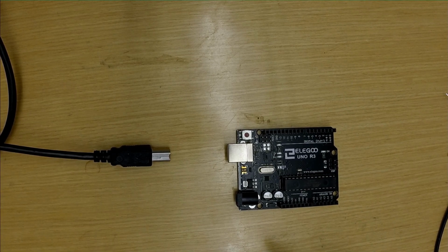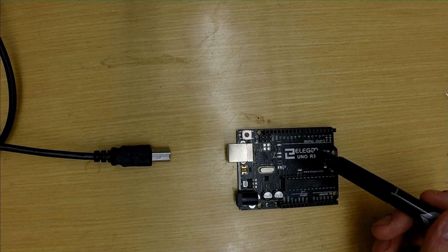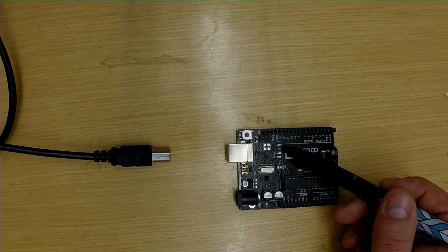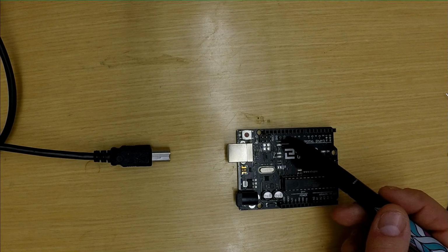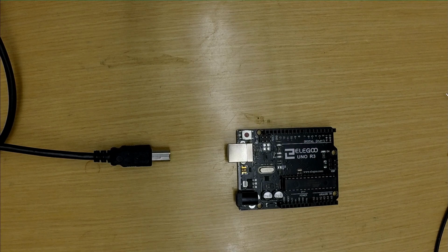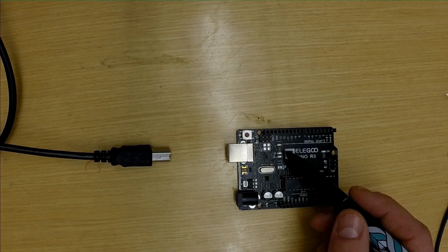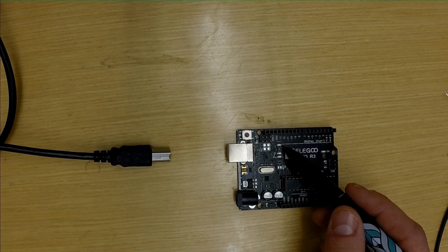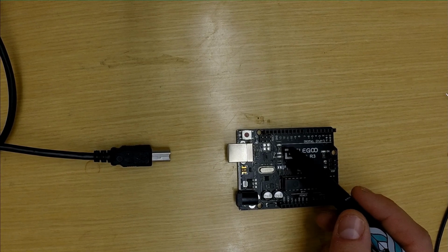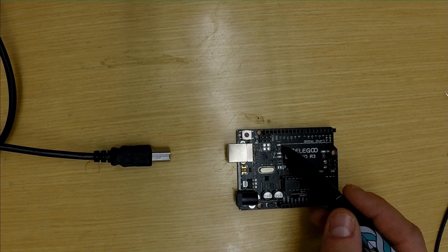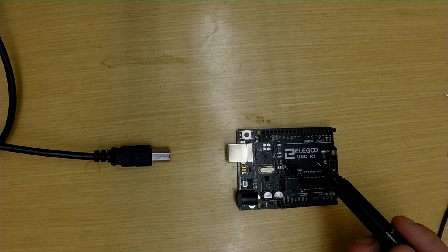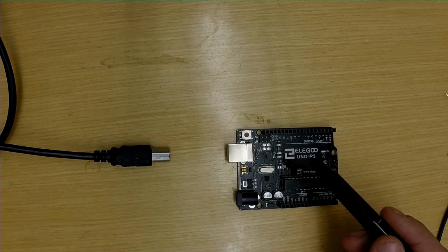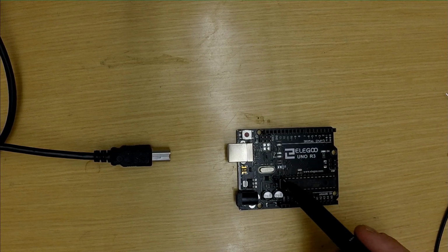Today what we're going to be focusing on is that there's actually a built-in LED right here that is connected to digital pin 13. So you see there's a pin labeled 13. If we connect something there, we can turn it on and off using that pin. And the creators of Arduino have also given us a nice LED that's soldered onto the board. So whenever we turn on pin 13, this LED is going to light up also. That's just a handy fact if we are troubleshooting to have that LED right there. We can essentially tell it to turn on and off, blink on and off, and we'll see if our Arduino is working and if we're able to upload code to it.